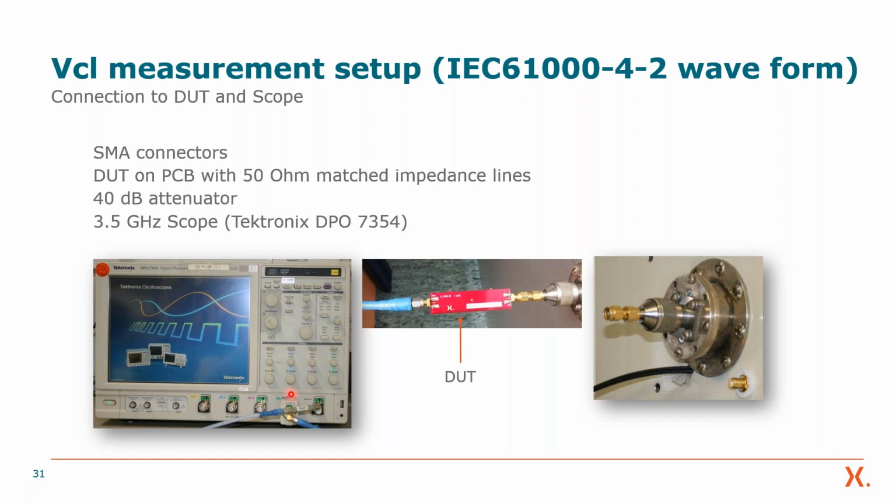Now, if you do not shield the gun from the scope or from the PCB, you will not get repeatable results, and you will definitely spoil your measurement results significantly.